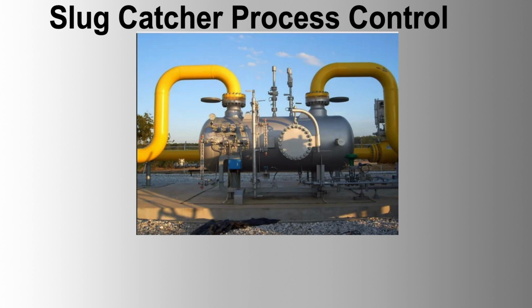1. Inlet flow feed-forward control, FFIC, feed-forward flow indication control. Objective: adjust the operation of the slug catcher based on anticipated changes in inlet flow from the well clusters. Mechanism: measure the flow rates from individual well clusters and calculate the combined flow rate entering the slug catcher. Adjust the inlet control valves accordingly to prevent overloading.